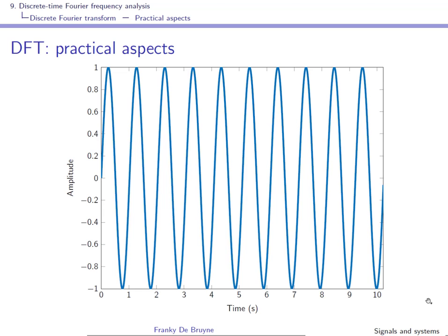So of course the frequency of the sine, 1 over the period, will be slightly lower than 1 Hertz. So here is the sinusoidal signal. You can indeed see that we cover 10 periods. Notice that this signal is indeed discrete, but this is not visible because we have chosen a sampling frequency of 100 Hertz.